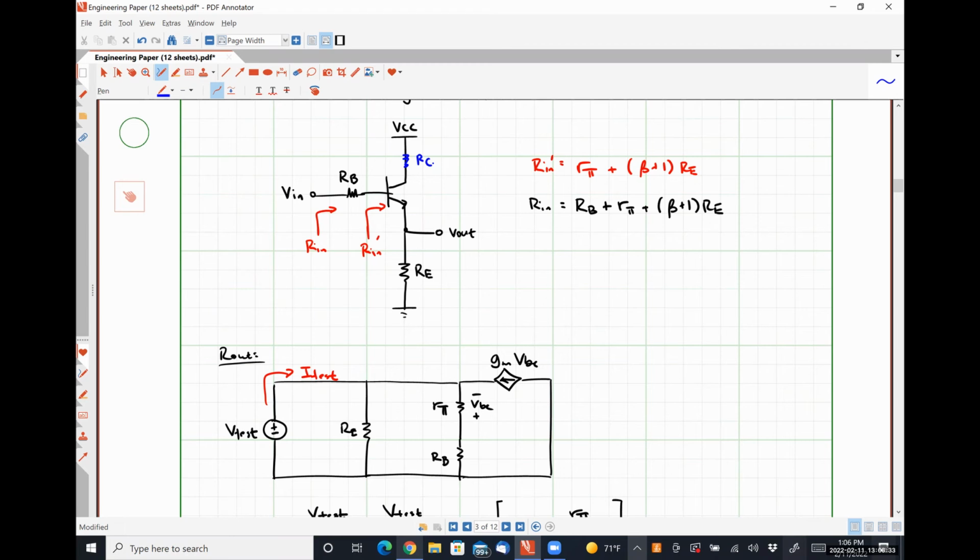So it doesn't literally change anything for the small signal at all. And you have something to eat up a little bit of variations, right? Because if you don't have a resistor here, anytime the power supply voltage changes, VCE changes by however much the power supply voltage changes. With the resistor there, VCE only changes by the ratio of that current.